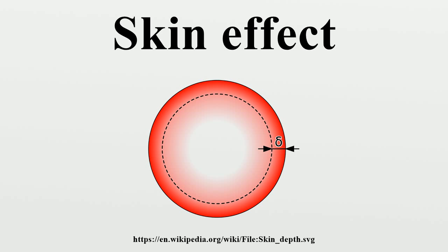This reduces attenuation of the propagating wave due to resistive losses affecting the accompanying eddy currents. The skin effect confines such eddy currents to a very thin surface layer of the waveguide structure. The skin effect itself isn't actually combated in these cases, but the distribution of currents near the conductor's surface makes the use of precious metals practical.